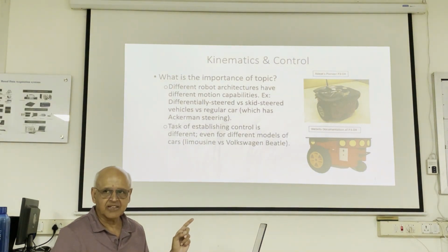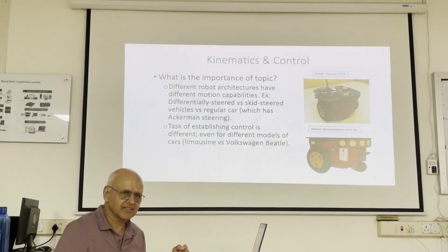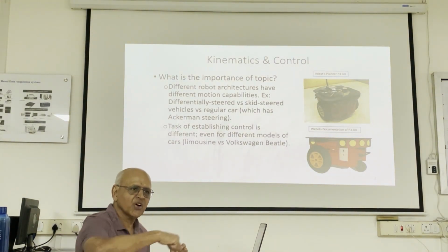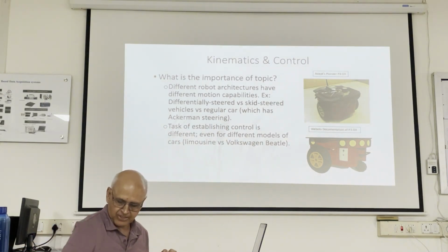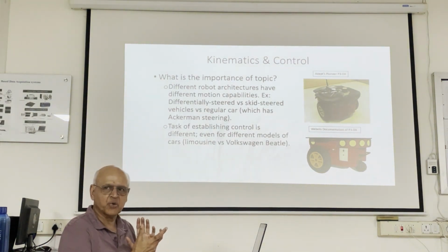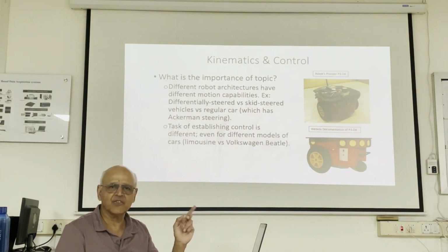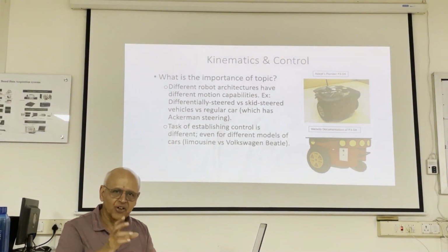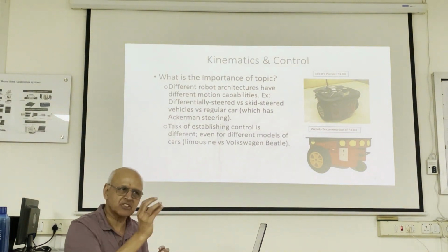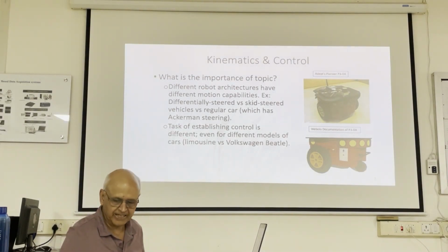Now, in a regular car, if somebody says, get to this spot, not possible. You have to go and come back, right? If somebody says, get to the next parking spot from here, no, you have to drive over and come back. But this one can. It can turn around in place and actually go there and then straighten itself out. So that is the beauty of a differentially steered vehicle. It is capable of very sophisticated contours, all with that circle concept. You know, little pieces of circles. A self-driving car can do circles, but it can't get to a spot immediately next to it.